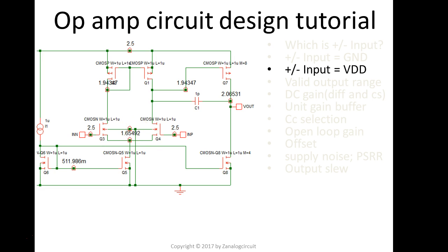By doing that, the VT of Q3 and Q4 increased. So that's the reason you see that if we keep the input voltage the same, we are able to push the source voltage lower. Now when you look at the VDS here, you get almost 0.3 volts, right? So now these two guys are in the saturation region, which is great.